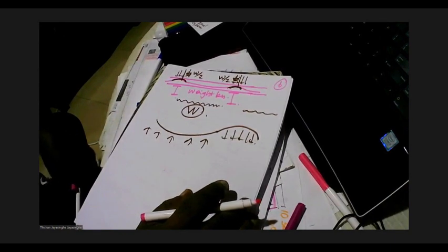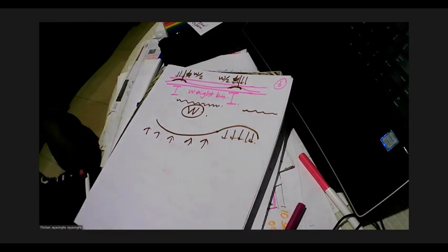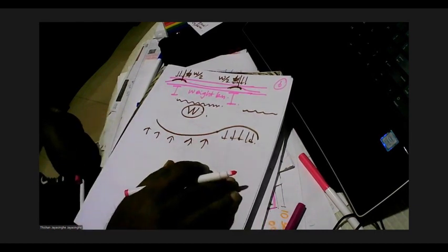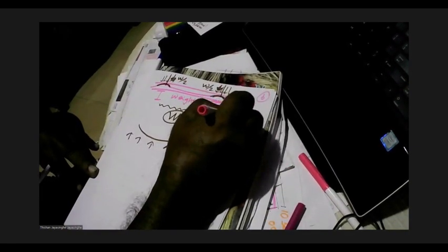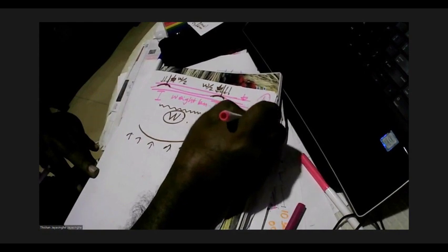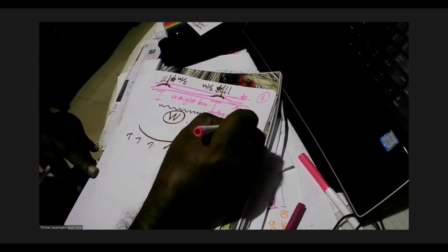Then whatever the deflection will come only from the live load and the finishes and the services. So you can have a thin slab of span over depth going up to about 40 to 45.